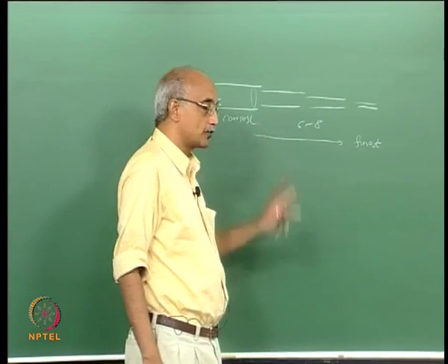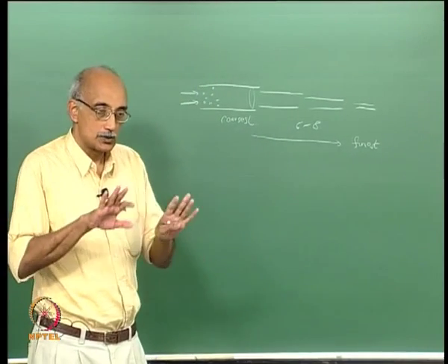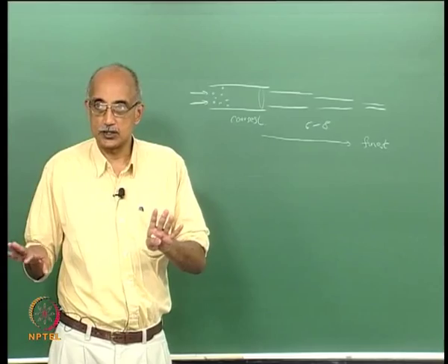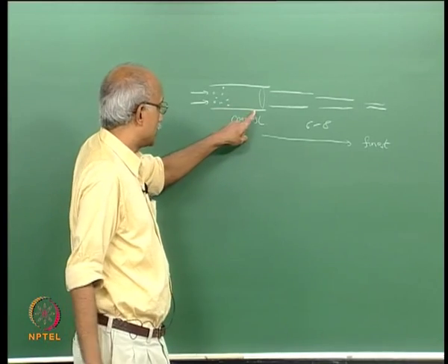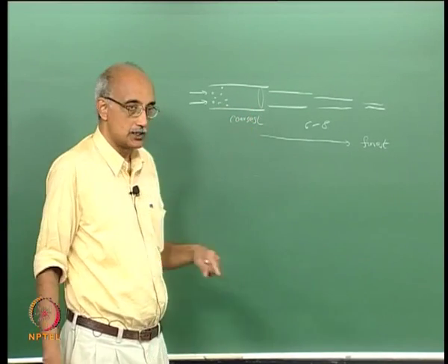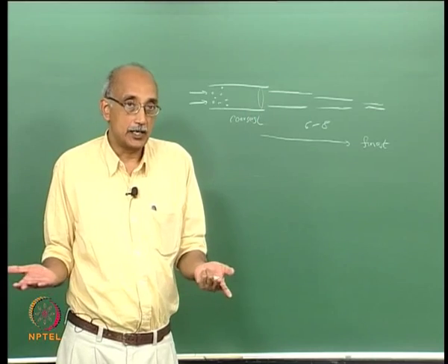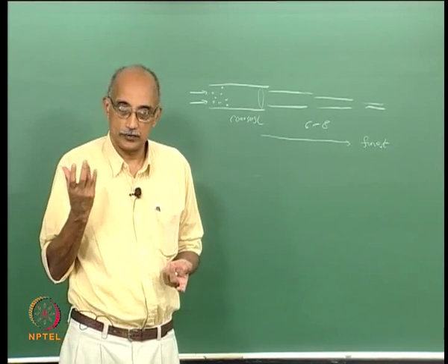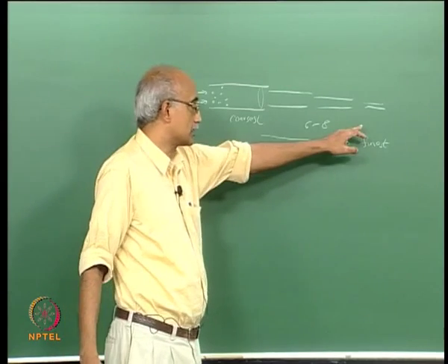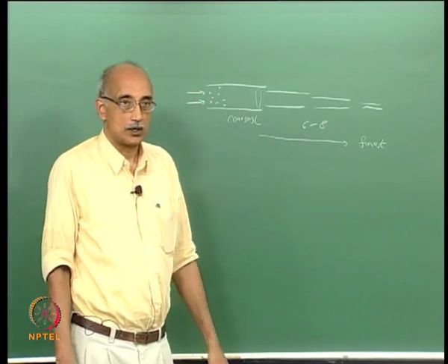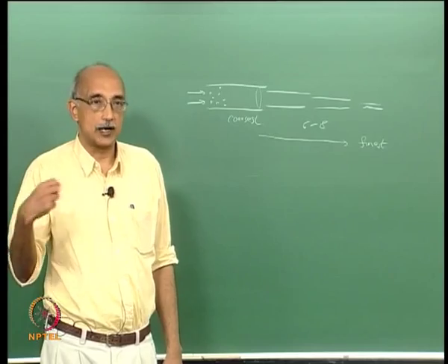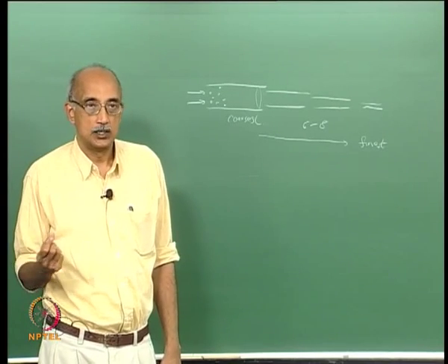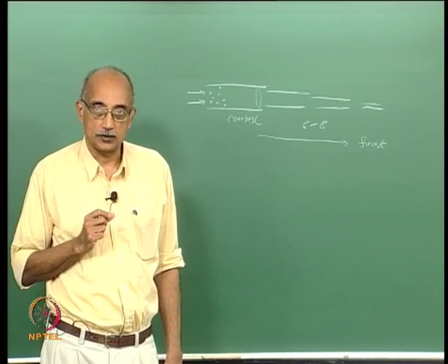This method is very powerful because you have now classified the sizes also. So, you can take the collector plate from the first stage and just look at it, maybe with naked eye or with an optical microscope. That may be sufficient because the particles are very coarse, whereas the particles that you pick up from the last stage are likely to be very fine. So, you probably have to take them in for SEM or TEM analysis to do the size characterization.